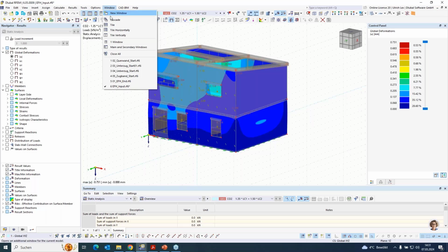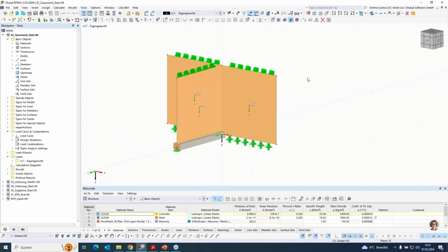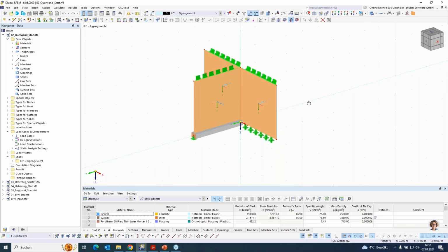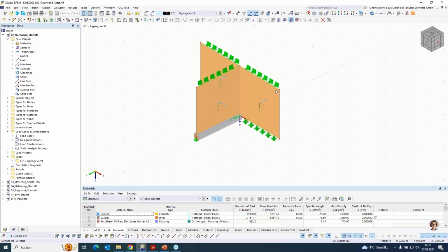and here the first one is a part of masonry where you have maybe some outer wall, exterior wall, and one interior wall. Mostly you have two different materials, maybe as I chose before, like a wall with 380 millimeters width, and for the inner wall, a different material with 170 millimeters. If you build up these walls, then generally the outer wall is created, and after that the inner wall will be created. So the connection between these walls is not rigid, I would say.